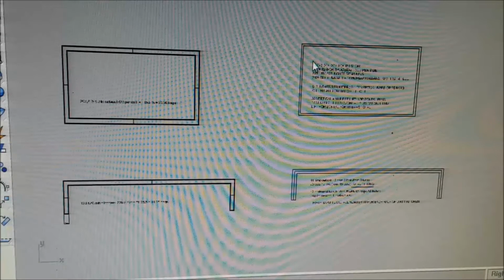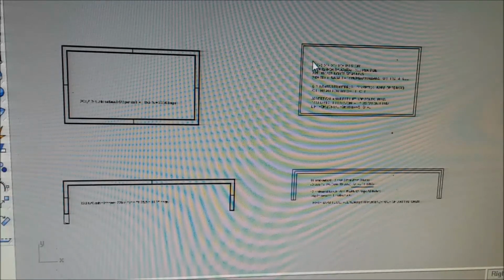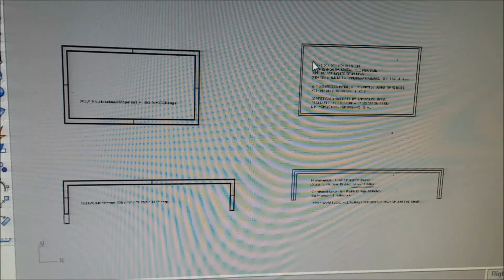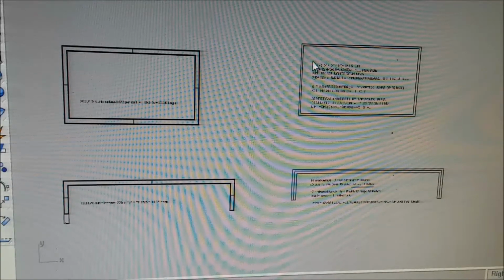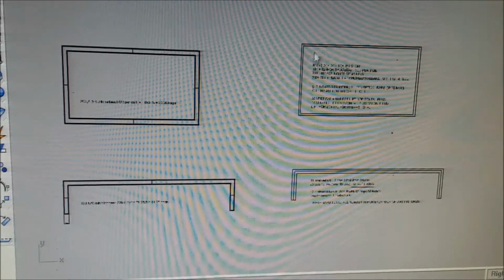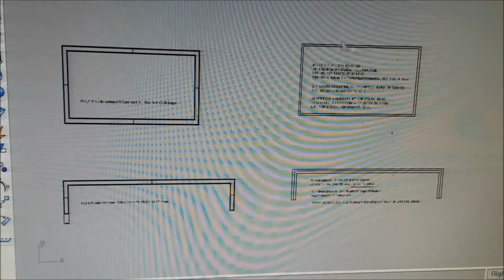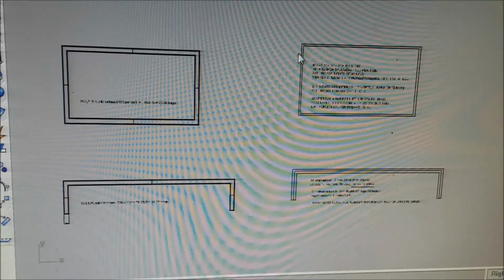Okay, you buy the concrete by volume. You figure out the bars, figure out the drops, reuse the drops that are over 30 inches. You're going to lose 16 inches of it to the splice, but that's another thing. We run our bars, a lot of things, instead of going straight across and straight down the length, we run them at a 45.